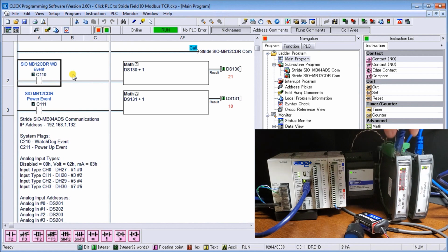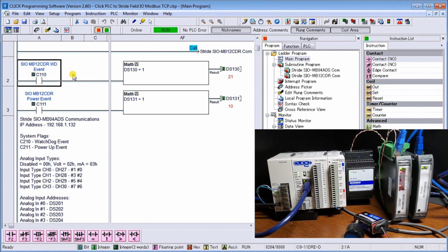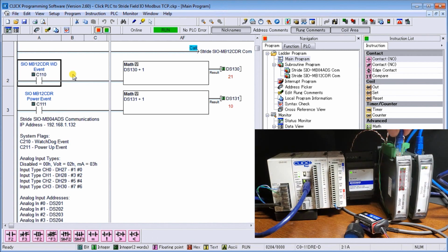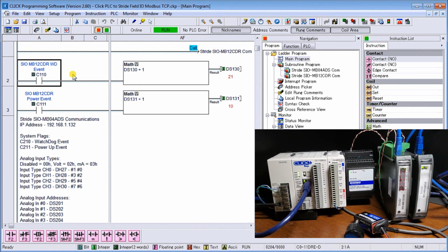And when I unplug it, after 3 seconds, what you will see is now my flashing indicator saying that, look, I have a Watchdog interrupt happen here. And then if I reestablish the communication, you will see, first of all, it clears that error, but then I have a count here saying, yes, I have a Watchdog event happen.